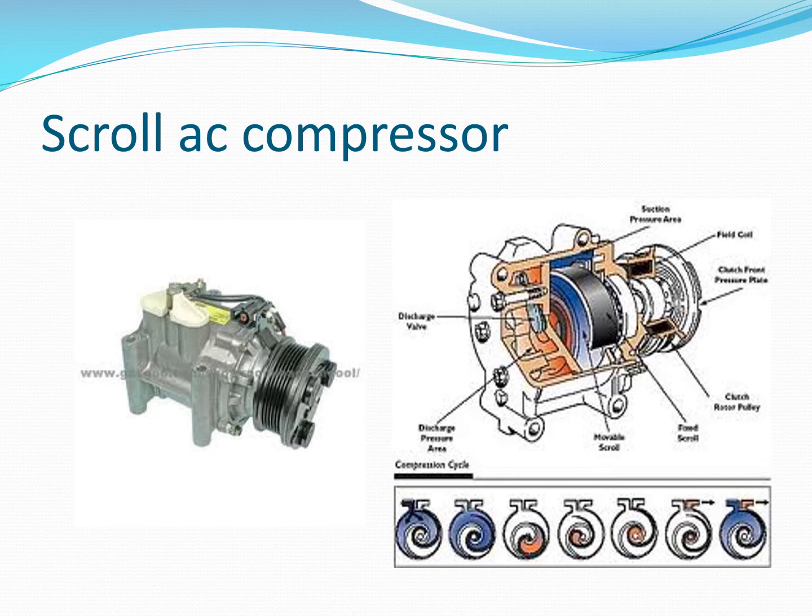And as that refrigerant gets pushed to the center, it is compressing the refrigerant because it becomes a much smaller and smaller space as it gets towards the center of the scroll. And so this system confines the refrigerant into a much tighter spot. So in theory, it's much more efficient and it takes less energy to rotate it.